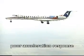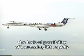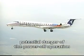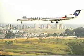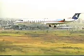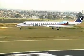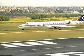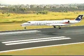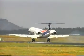So add the poor acceleration response of the turbofan to the lack of possibility of increasing lift rapidly and the potential danger of the power-off operation, and you have reached 3 ways in which pilots of turbofan aircraft are not as lucky as the friend with the turboprop. Together, these facts are far more than enough to distinguish and emphatically mark the difference in one of the most significant aspects of operation of our 2 good aircraft power plant installations, the approach qualities.